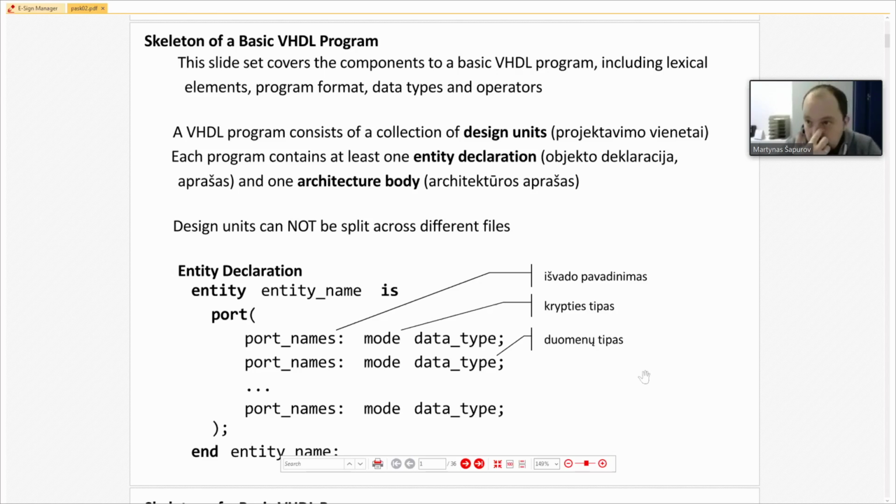In laboratory works using assembly for microcontrollers, you learned that you have to shift some value into a certain register, then you can add something and read something from another part. Also, while doing laboratory works with interrupts, you were manually changing your program counter, jumping from a certain point to another point and then returning back. That's why you were saving some values which are in the W register and so on.